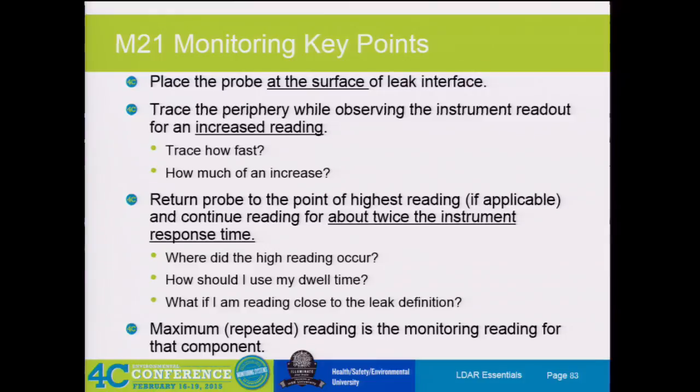So I'm not saying do it wrong, but speed up more and go faster around the bonnet where it's very static, it doesn't move often, because you're less likely to find leaks. We find maybe 1 or 2% of our leaks on the bonnets, versus the other 98 or 99% is all in the packing in the stem area.